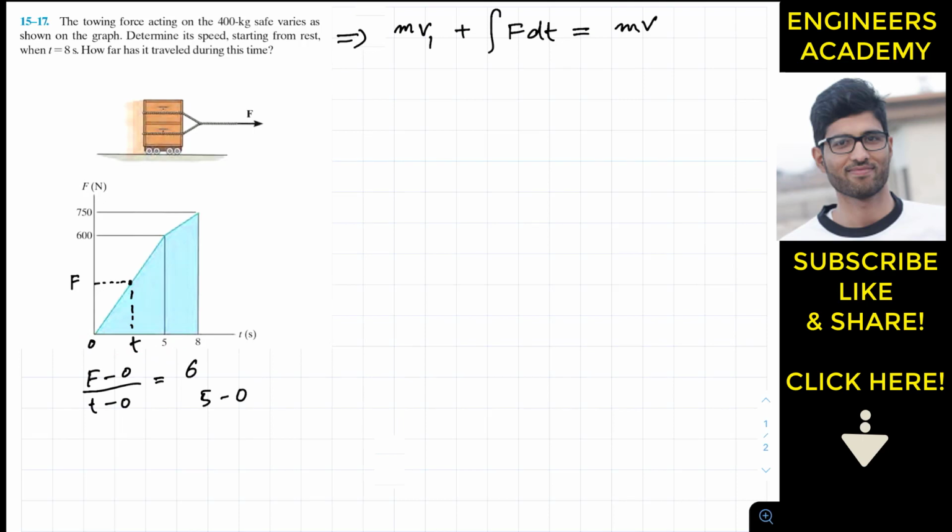So this is 600 divided by 5, and 600 divided by 5 gives us 120. So this is 120, and this will be (F minus 0) divided by (t minus 0), so F divided by t. From this equation we can write that F is equal to 120t. This is the force equation for the interval when t is greater than 0 and less than 5 seconds.